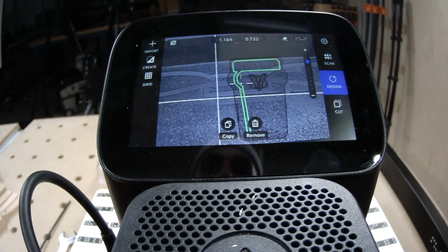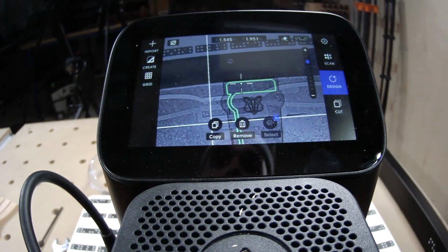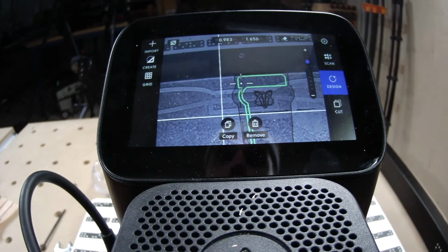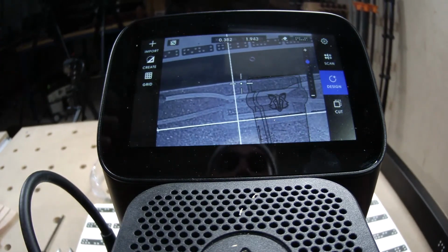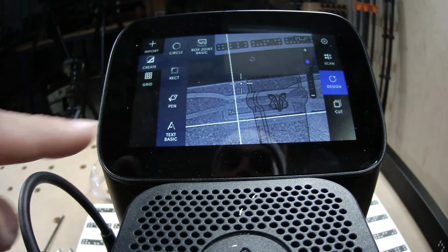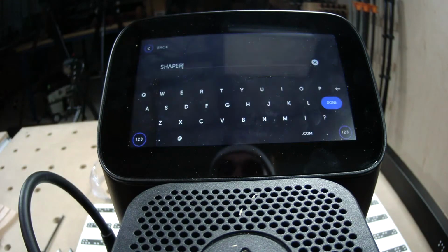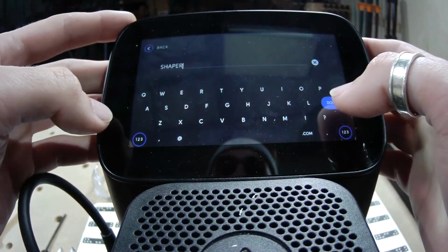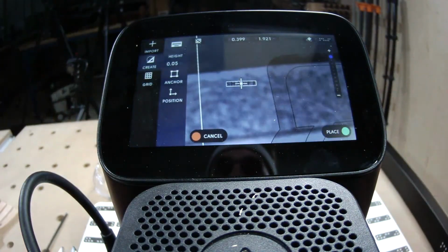When I hit place, now I have it aligned with that shape and anywhere else I want it to be. So that's a super cool little pro tip that I like to do, especially when your project's half visual alignment, half the other. Another example where that could work is if you've got text and you want it exactly, say, 10 millimeters below another piece of text, but you want to just visually compose it left and right.